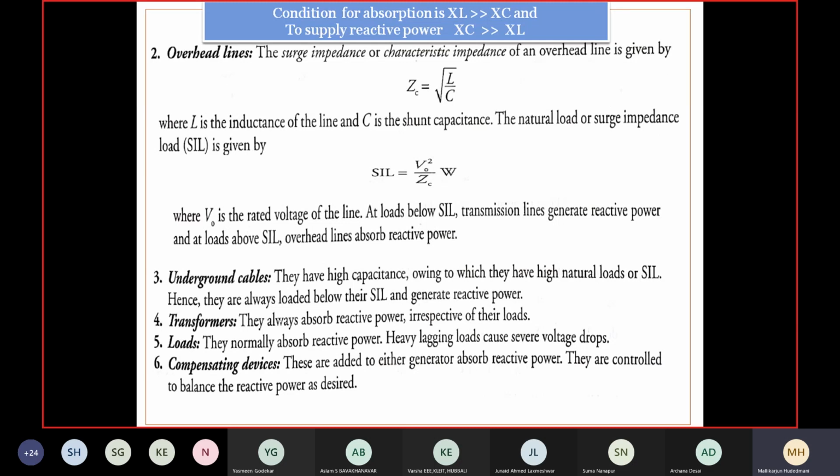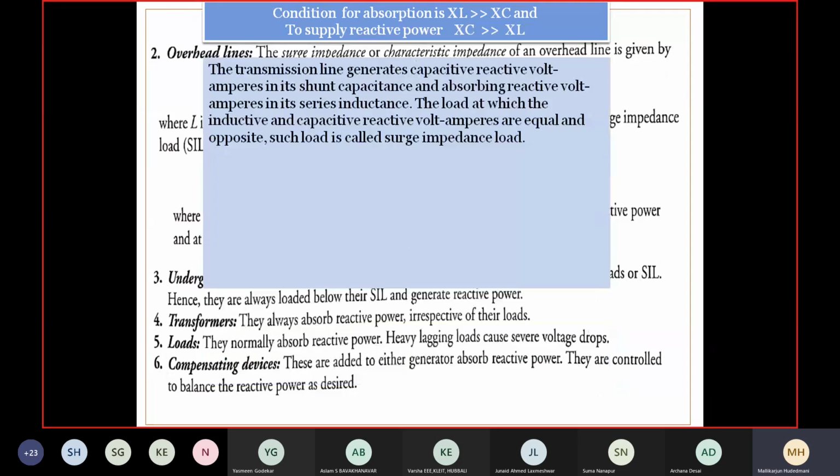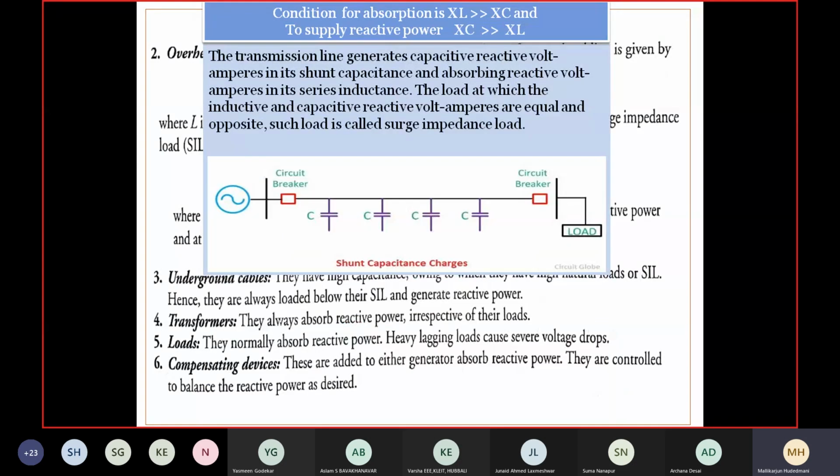Because of that structure of different layers of insulation around the conducting element, when this conductor is buried and put into operation, it has an opportunity to generate reactive power. That is what is noticed here. When I have a transmission line, which I was showing you with a particular distributed transmission line model, that is going to dominate in the earlier case.